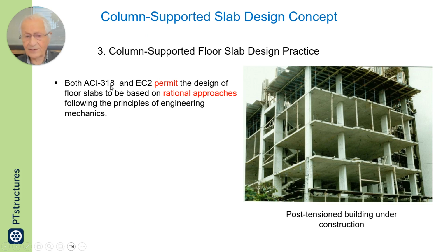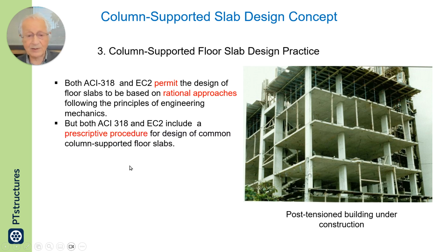Both ACI 318 and EC2 permit the design of floor slabs to be based on rational approaches, following the principle of engineering mechanics. Why do I say this? I want to bring it up again, that you need not follow the prescriptive method described in either ACI 318, which is the strip method. You can use finite elements or use a top and bottom mesh over the entire slab, as has been done primarily before.